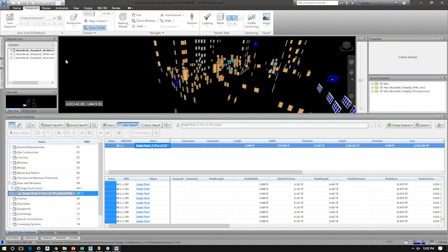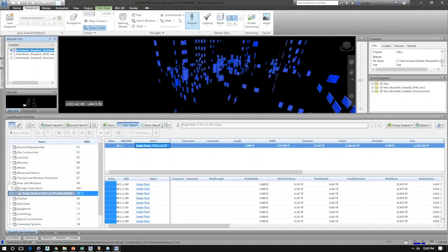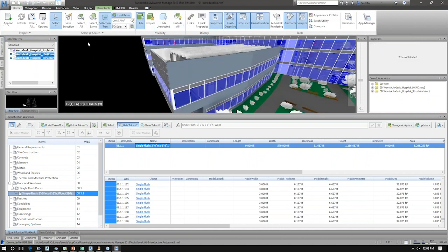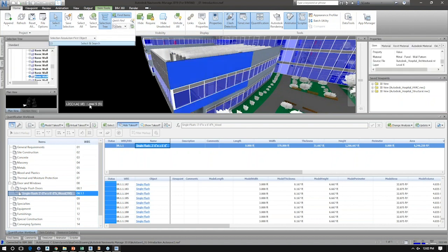The one button push of how to do this is the following. I can go to hide, unhide all, hide this information, choose my entire file for the architectural model and run what's known as a model takeoff, right? And what it's going to do is it's going to build a brand new category just called what the name of the file is and create an entire set of quantifications based on the element type names. What that allows me to do is then export that out to an Excel spreadsheet, which I'm just going to jump to and not create because it takes a while to generate.